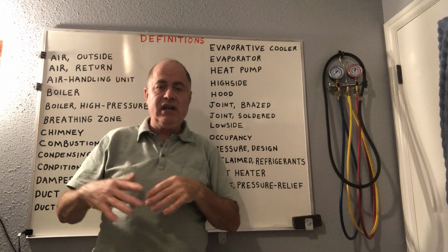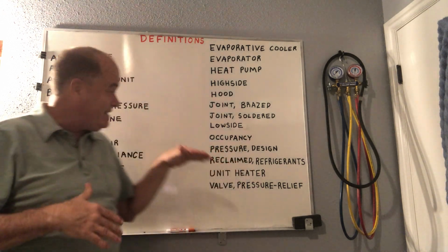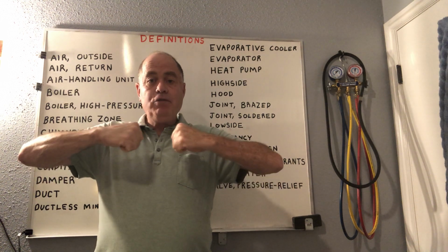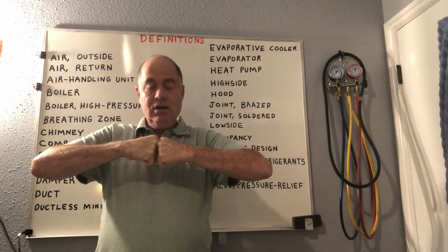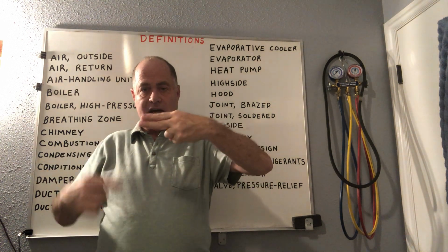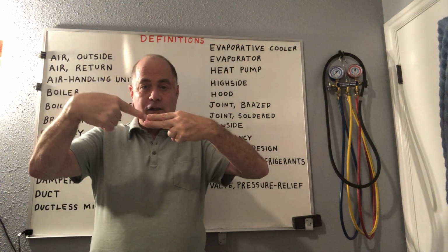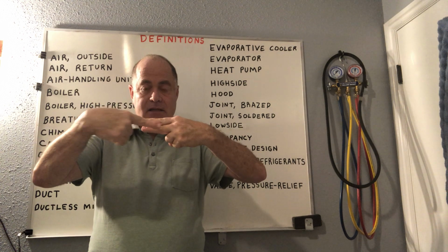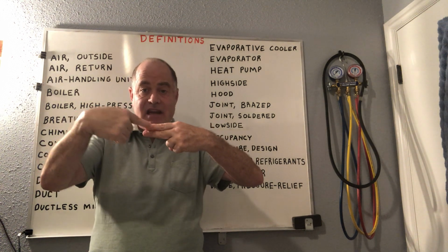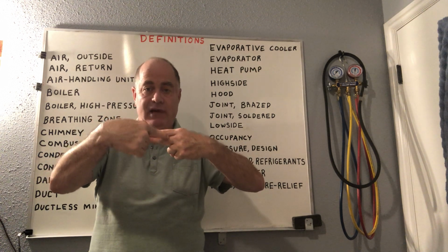And just so you understand what is the difference between brazing and welding, welding is this. You have two pieces of metal you're trying to join together, and as you go to add your filler metal here to the base plates, you're going to actually melt some of the metal that you're working on and then add some of that alloy to it.